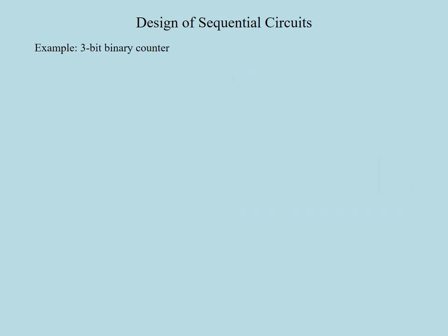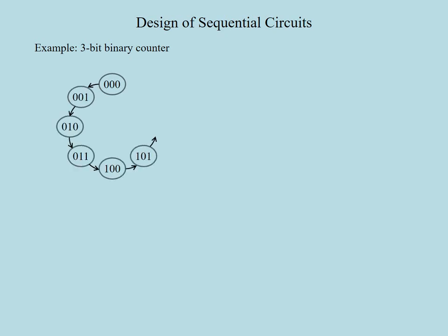As the next example, we will design a 3-bit binary counter. A counter is a sequential circuit with no inputs. Such circuits go through a prescribed sequence of states by switching to the next state at every clock pulse.